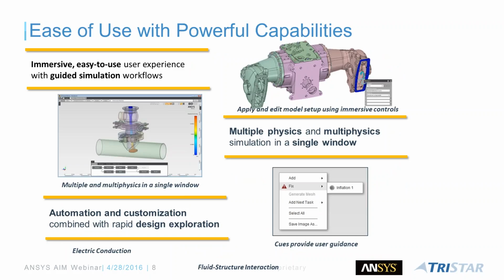So you would essentially open that in your Creo environment. You have a Creo file, right, and then take it to ANSYS. And ANSYS has these process templates, right? So let's say you want to do a structural analysis only. All you're worried about is the stress and the deformation. You would just choose that template. Or if you're more into fluids, or if you have a multiphysics problem, you would choose that appropriate template, and it automatically gives you some guided workflows that you could choose, and it will just walk you through it, right?